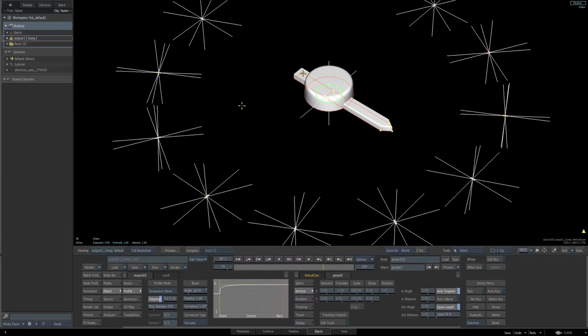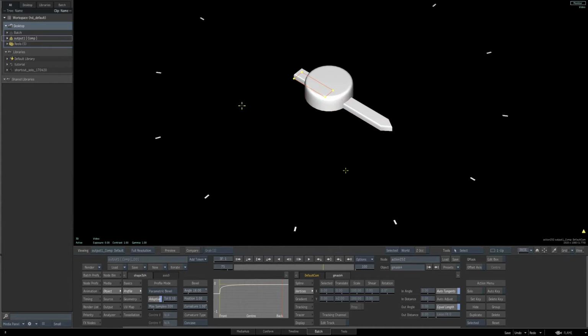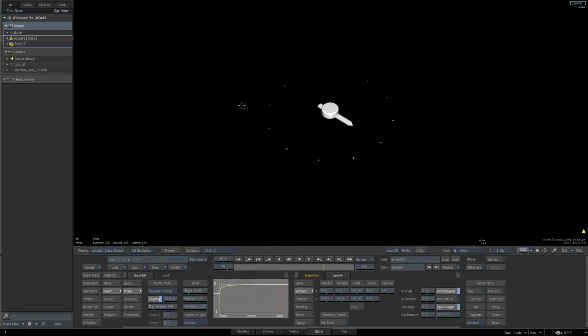Select the shape in the back. Once again, the curvature goes to 1, the maximum. And then we'll set the angle for this shape to 18 also. So now we've adjusted the bevel profile for all 3 shapes. Turn off the icons once again by hitting the I key twice so we can clearly see what we just did. So now we're done with the modeling part of these shapes.